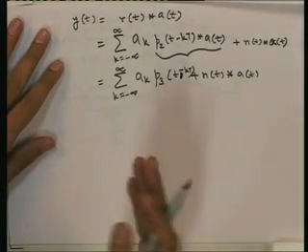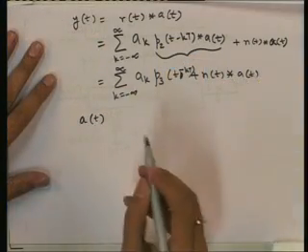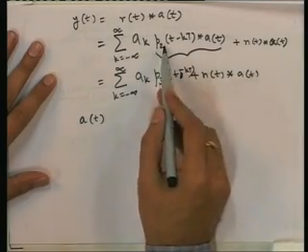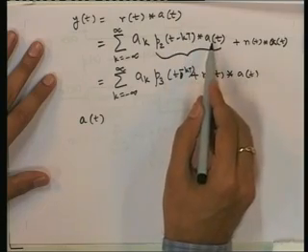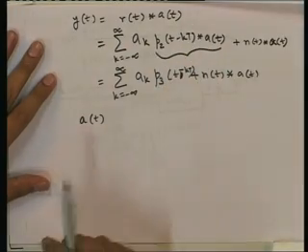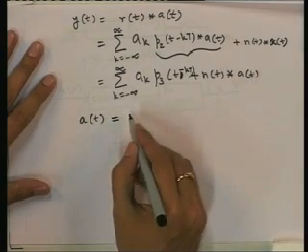Okay. So now we want to see what a(t) should be. How should we actually design the receive filter? What is the criterion? Before going into that, we will first assume something: we will assume the receive filter is of a certain form, analyze the case, and then prove that it is the best thing to do. So we will take what is called the matched filter. So a(t) is matched to this pulse. a(t) is being convolved with this pulse, if you see here. So we will take a(t) such that it is matched to p2 in some sense.